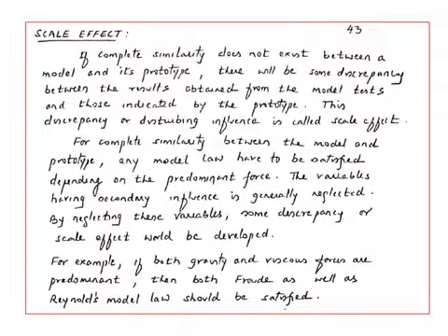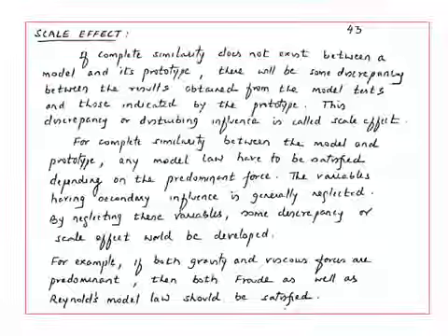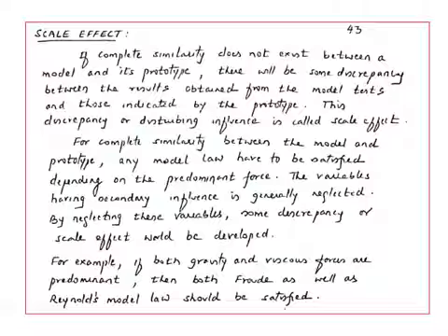The variables that have a secondary influence are generally neglected. So there may be some influence of viscous forces also. Where we are taking the Froude model, we are neglecting the other variables, so only the gravity force we are taking into account. By neglecting these variables, we get some discrepancy, which is known as the scale effect. For example, if both gravity and viscous forces are predominating in the flow phenomenon, then the Froude model law as well as the Reynolds model law should be applied.